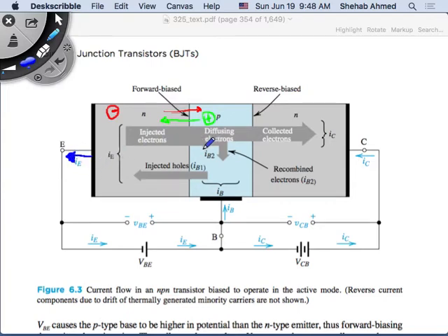But one thing we will note is that we create this device with a very small base width, for a specific reason. So what happens if the base width is small? That means the amount of holes that I have in the base is small. Right? I've added acceptors, but I have a small amount of acceptors. I already have a small width there, right?